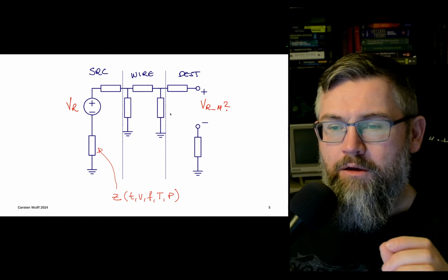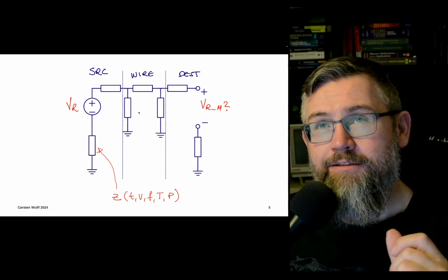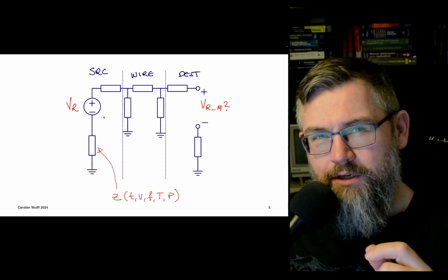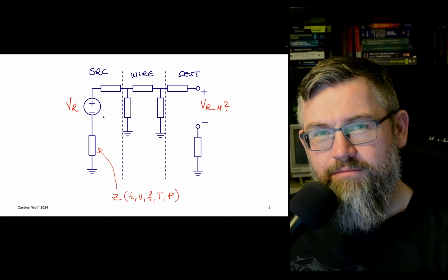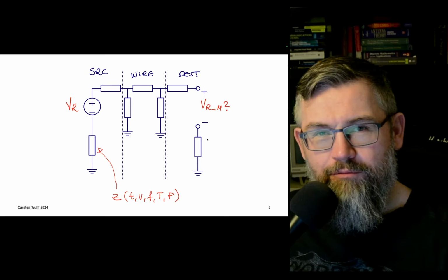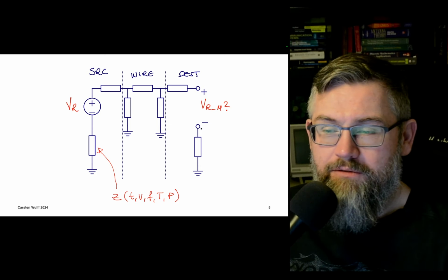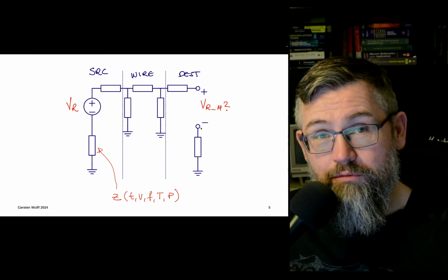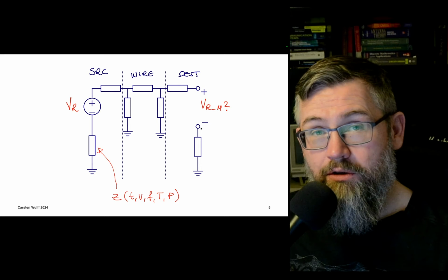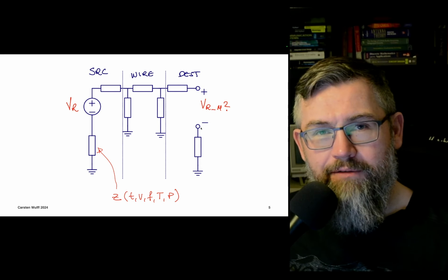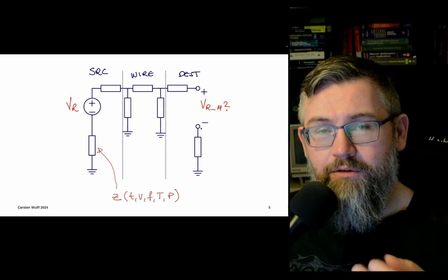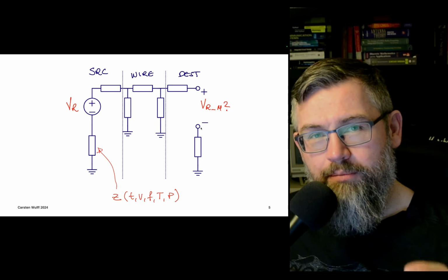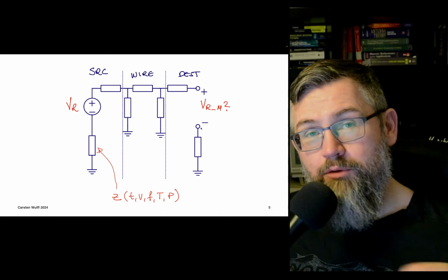Anyway, that means that if I want a robust reference, then I don't really want to distribute voltage across the chip, because I can't rely on the ground being the same, especially because, for example, in a step-down converter going from 3.6 volts down to 1.2 volts, and we use a DC-DC or a buck regulator, then the buck regulators are PWM based. Well, not PWM necessarily, but at least they have a switching node. And that has a tendency to pump currents into ground. So that ground locally will bounce up and down.